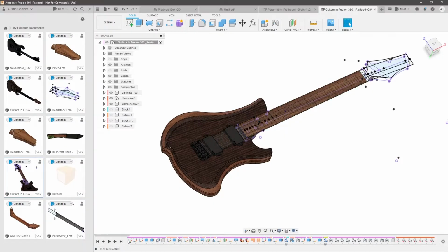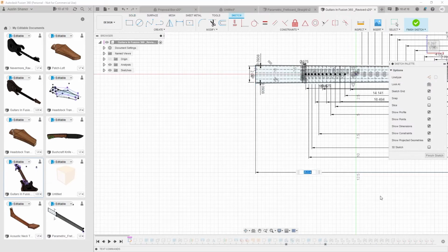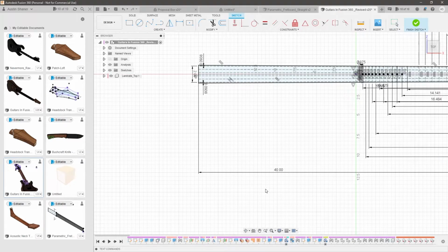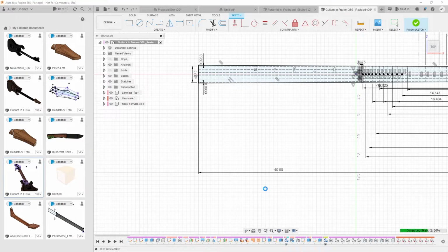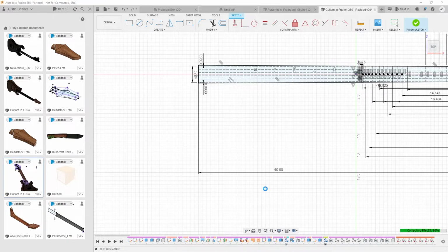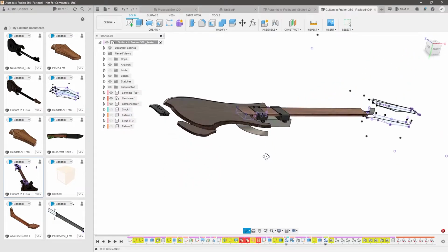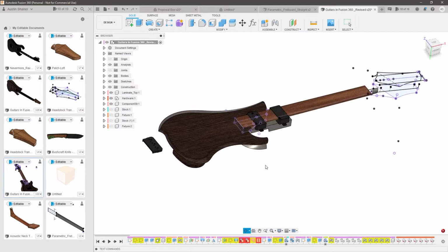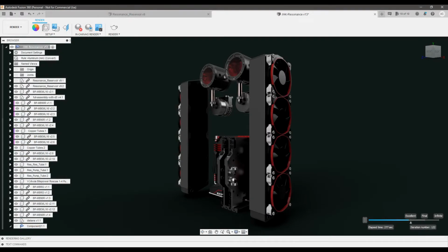The drawbacks to a top-down approach, however, is that it can be very resource intensive. All dimensions are contingent upon all other dimensions and locations of features in your design. This introduces more opportunity for calculation errors, because when you change the dimension of one feature, the other features that were dependent upon that dimension may now be impossible to create. All that being said, there's really no correct method here. Each have their pros and cons, and the approach you should use depends on the design you're trying to create.